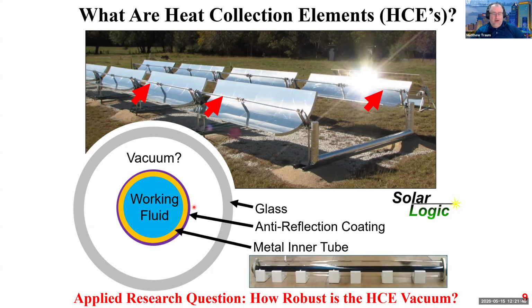And they were asking the question, well, is there actually a vacuum in this space? Did the manufacturer evacuate the space, or is there air in here, right? And if there's air, there's the possibility for even convective heat transfer, right? The motion of air transmitting the heat. And there's definitely the possibility of conductive heat transfer through the gas layer from the surface to the glass, and then conduction through the glass to the outside.